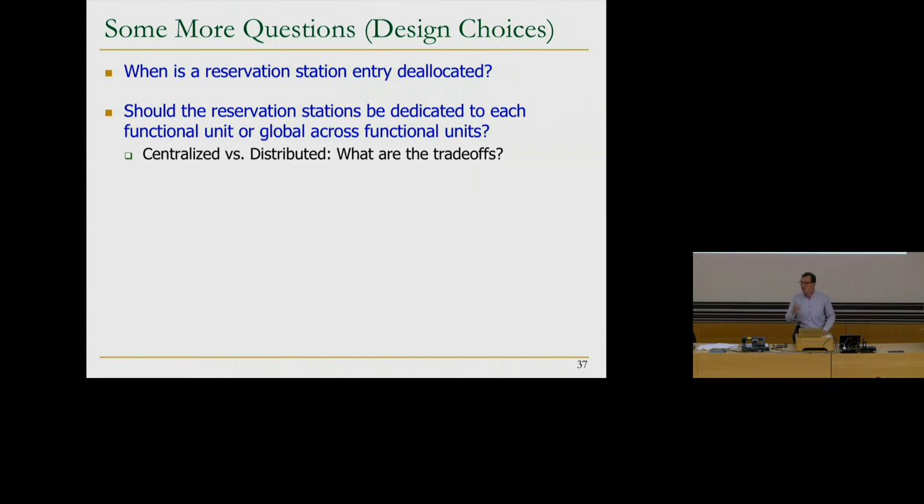As you get more centralized, the reservation station needs to be more general purpose, and also bigger. As a result, it becomes difficult to design. So current machines usually make the trade-off such that the reservation stations are distributed, but they may not serve only 1 adder. For example, an adder reservation station may serve multiple adders, 4 adders, as opposed to only 1.